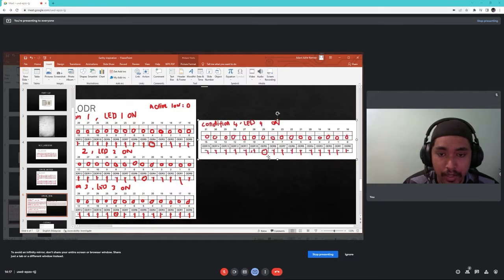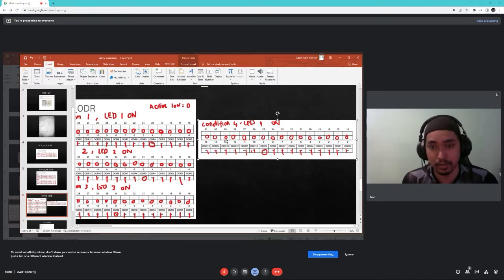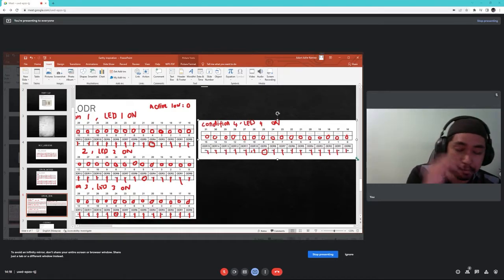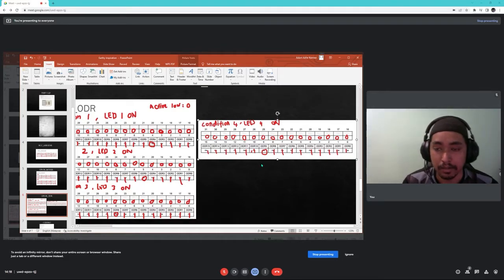Alright. So on port 9 we need to put 0 because we want to turn it on, since this is active low, and like usual on top of the board here we just mask it with 0 because this is not the condition to turn it on. We put 0 on port 9, and the rest of the ports we need to put 1. We need to divide it by parts of 4 so we can easily see what the number is.